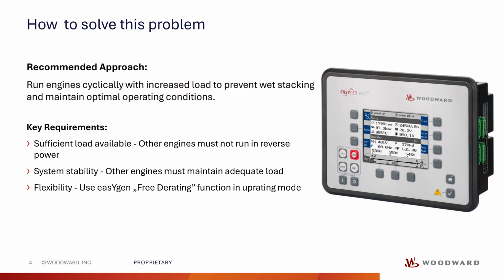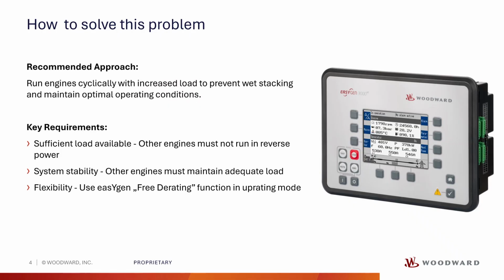To solve this problem, it is recommended to periodically run the engines at increased load. By periodically increasing the engine load, we raise the operating temperature, burning off excess residue, and maintaining optimal operating conditions. However, to do this safely, we need to meet a few key requirements.